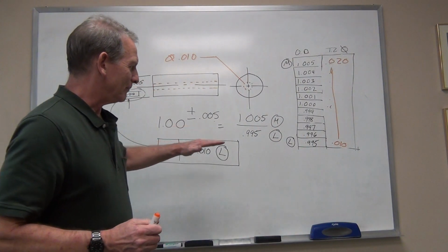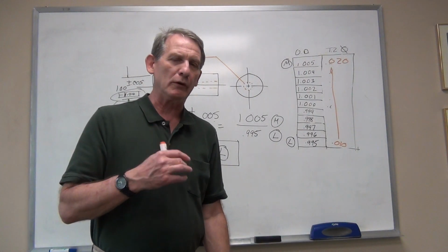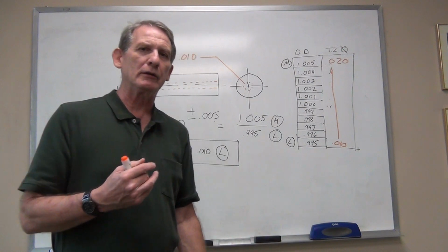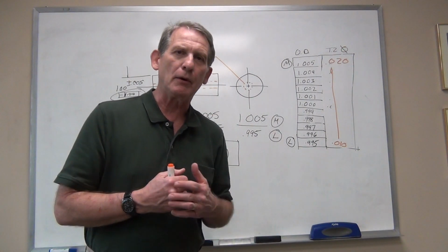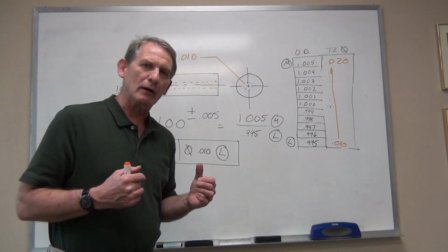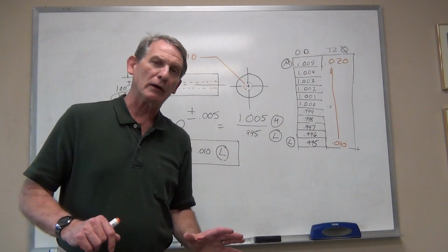Now again, this probably wouldn't happen. There are instances where you do use this. It's used to prevent thin wall conditions when you're drilling a hole into a thin component. And it works very well in that regard, but you won't see a least material condition modifier used very much at all.